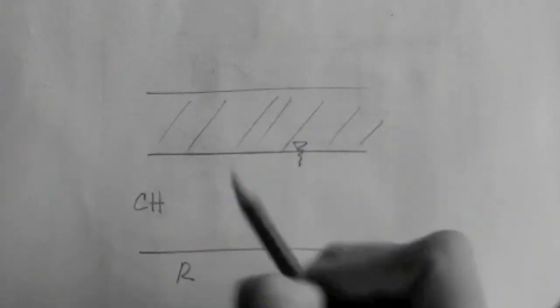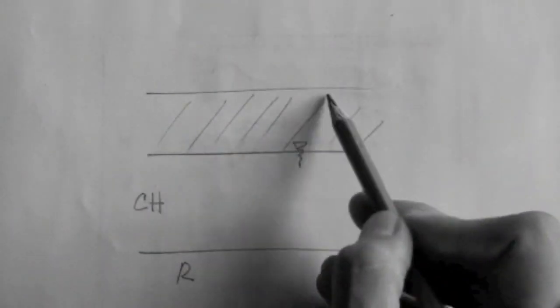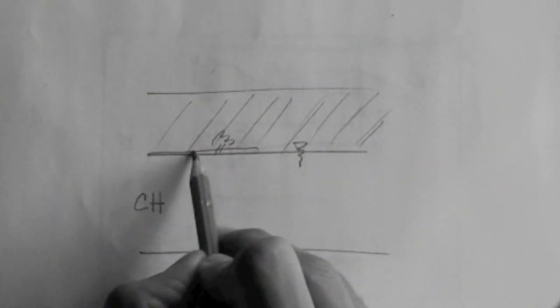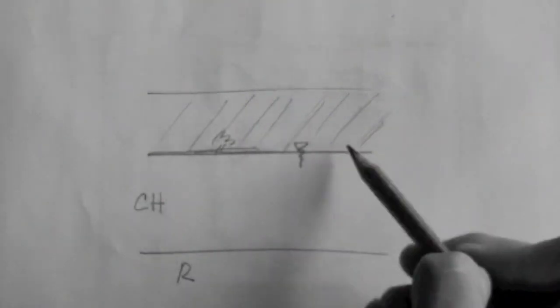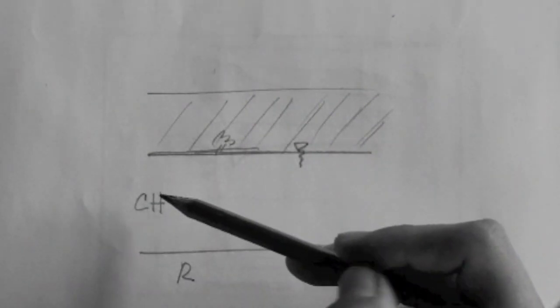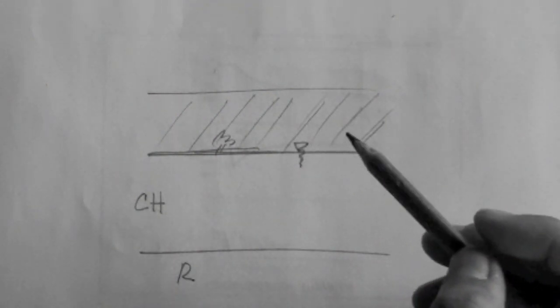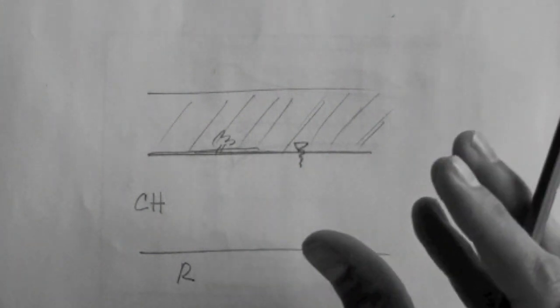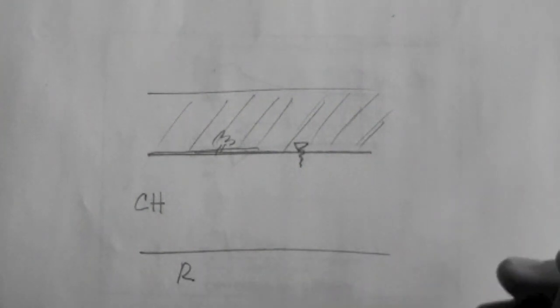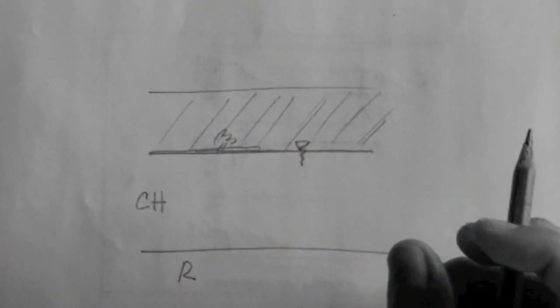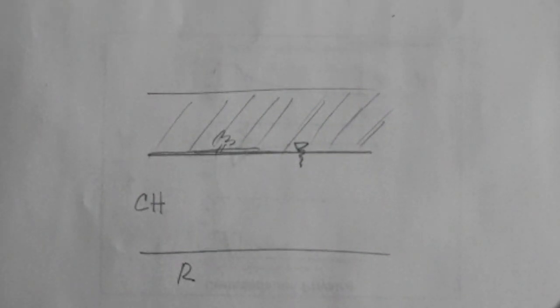We know that because this is clay, its permeability or hydraulic conductivity is very low, so we can expect undrained conditions, and we can expect the clay layer to squeeze, to consolidate, okay, but not immediately. It will take time because the hydraulic conductivity is low. So consolidation will take some time, maybe months, to finish.